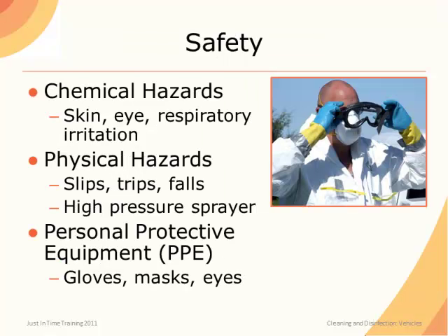Safety concerns during C&D of vehicles include personal exposure to chemical disinfectant products, which can cause irritation to the skin, eyes, or respiratory tract. Personnel cleaning vehicles should wear protective, waterproof clothing and appropriate personal protective equipment, such as rubber gloves and eye protection, when handling, mixing, and applying disinfectant solutions. Physical hazards such as slips, trips, or falls from slippery surfaces can also occur, as can injury from high-pressure sprayers.